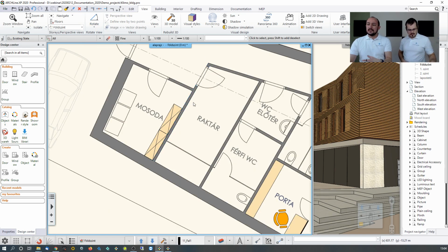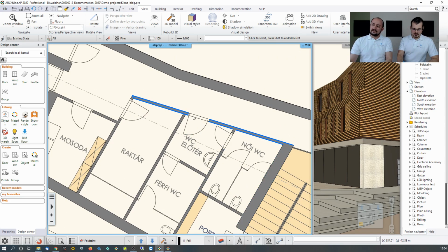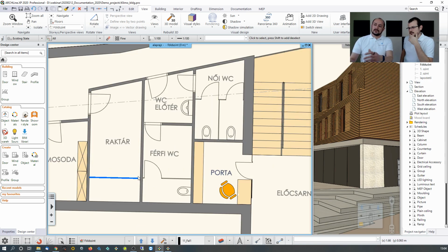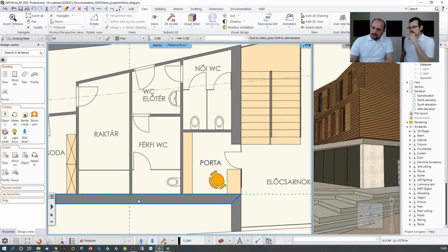This is what happens. And whenever I would like to rotate again and define another horizontal line, like this one on the corridor, I can go back, say rotate and pick 2 points, and that's the new horizontal. You can at any time define a new horizontal line by picking 2 points, and the software will keep rotating the content. And if you made a mistake, as I just did, then I pick the 2 correct points, and now everything is fine.